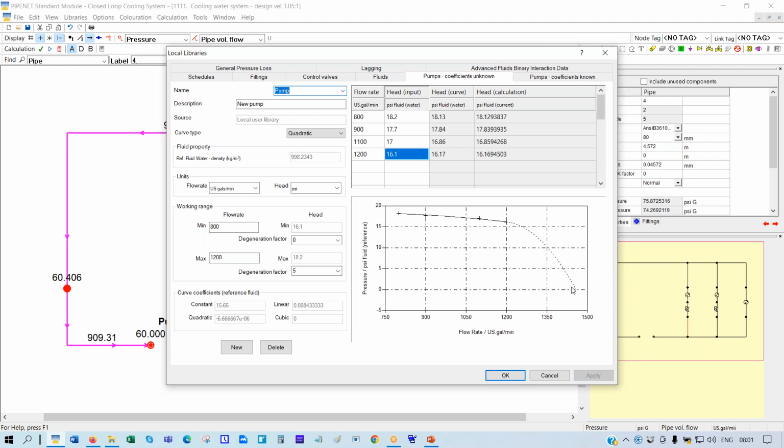See, it provides a dotted line, because essentially this is an unstable part of it, but your pump manufacturer should be able to give you a rough curve for how the pump may operate above the maximum recommended flow rate. And you can change that. If I make that 7, click on that. So you can adjust this value to match what the pump vendor gives you.